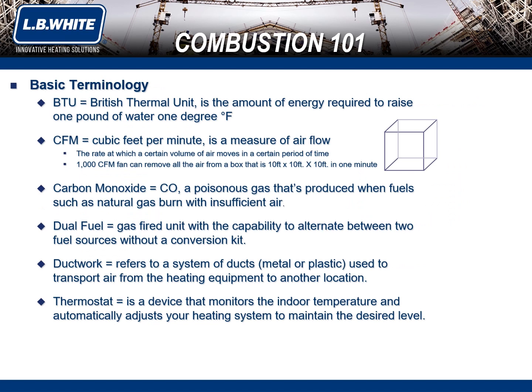Now we're going to talk about some basic terminology when talking about heaters. BTU is short for British Thermal Unit. It's the amount of energy that is needed to rise 1 pound of water by 1 degree Fahrenheit. 1 BTU is approximately equal to the energy released by burning a single match. CFM, cubic feet per minute, is a measure of airflow. For example, a fan with 1,000 CFM can remove all the air from a 10 foot by 10 foot by 10 foot box in 1 minute.